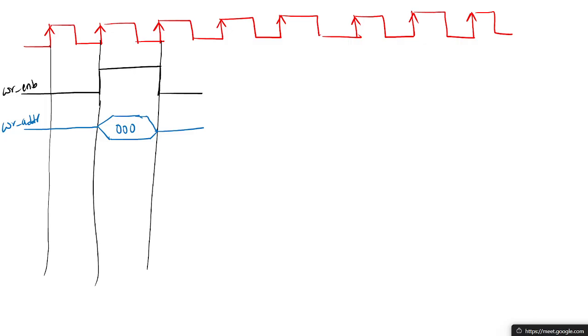And after that, next is data in, which is data underscore in. We need to provide the data, no? So what type of data do you need to write into the RAM? Let us take this is 8 bit data. Let us take my data is 8'b1111_1111. For readability I'm representing it like this. 8 bits of data.